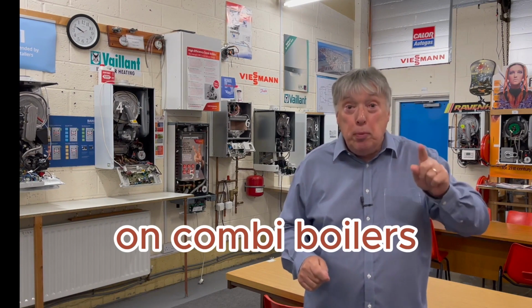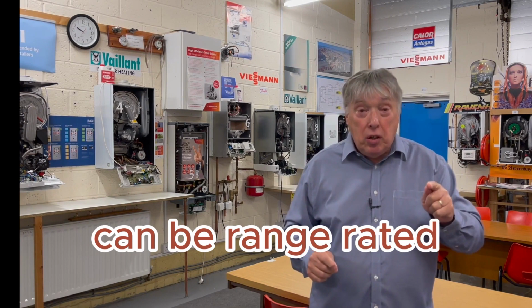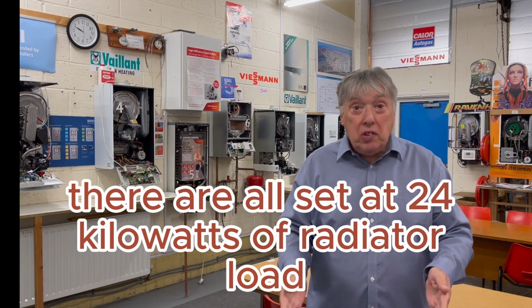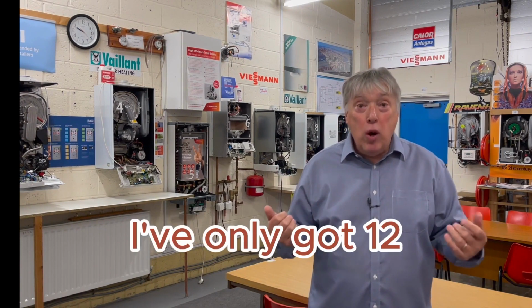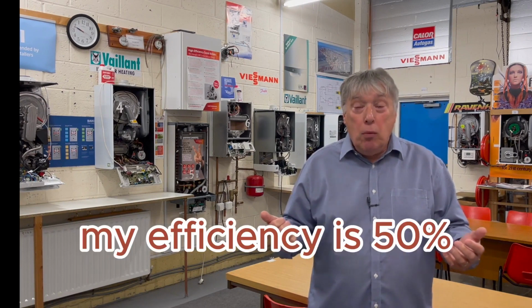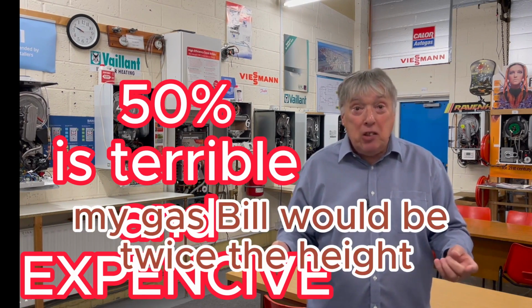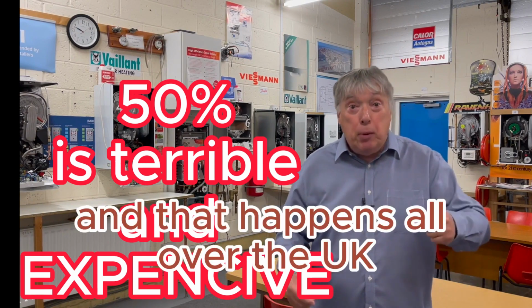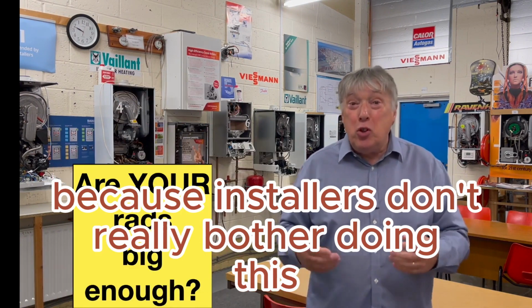Because we know on Combi boilers, a lot of them, in fact most of them, can be range rated. When it comes out the box and it's on the floor, they are all set at 24 kilowatts of radiator load. But as you can see here, I've only got 12. So therefore, my efficiency is 50%. And if I did nothing, my gas bill would be twice the height or twice the amount. And that happens all over the UK because installers don't really bother doing this.